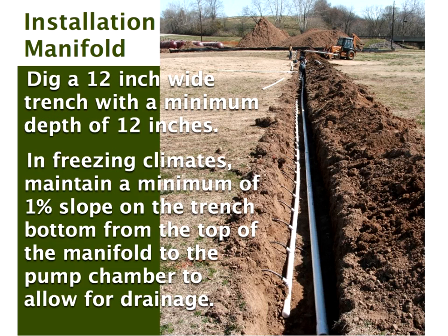Okay, Dan, what I'm concerned about is biofilm building up in the soil. The bacterial and biological mat around the dripper is the reason that I'm saying, put in as many drippers as you can. That's the reason behind that argument.